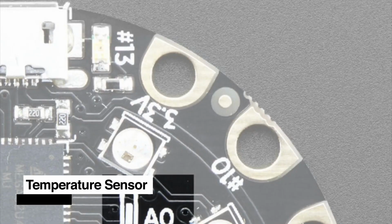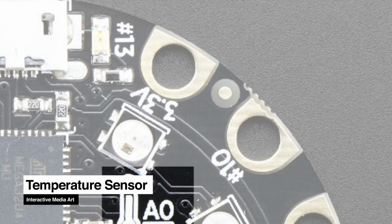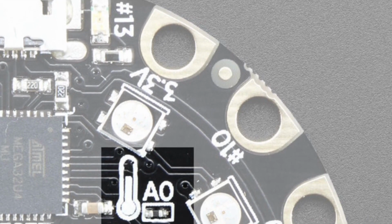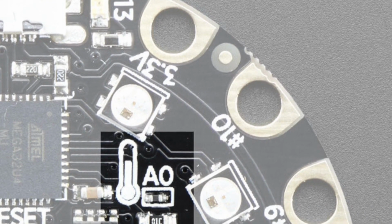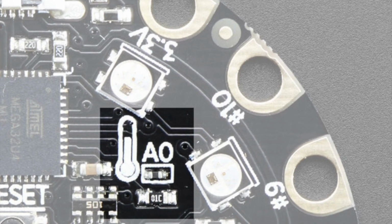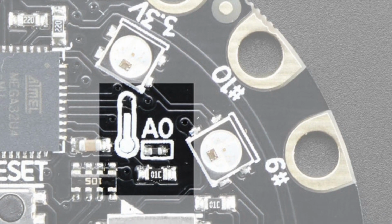The Circuit Playground also comes with a temperature sensor. It is a thermistor, which is a resistor that changes its resistance based on the temperature. It's easy to calculate the temperature based on the analog voltage on analog pin A0. There's a 10K 1% resistor connected to it as a pull-down, and you can read the analog value and calculate the temperature with the beta constant, or just use the Circuit Playground library.